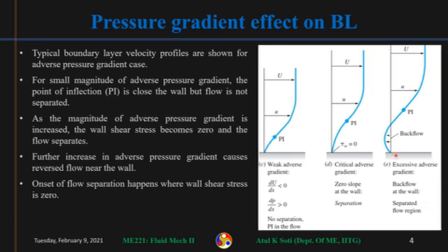So this kind of flow is called separated flow. Why? Because we say that here the boundary layer has separated. We could imagine that the boundary layer is starting from somewhere here, in a rough sense. So the boundary layer has separated. We don't have any boundary layer here because backflow is happening now. Okay, so this is called the separated flow region, where there is some backflow happening at the wall. Okay, so you can see that backflow will start when this happens.